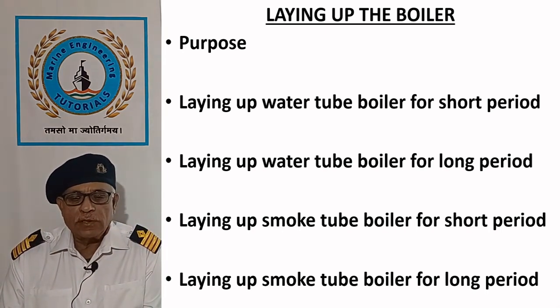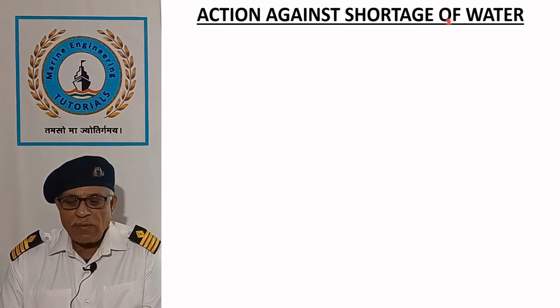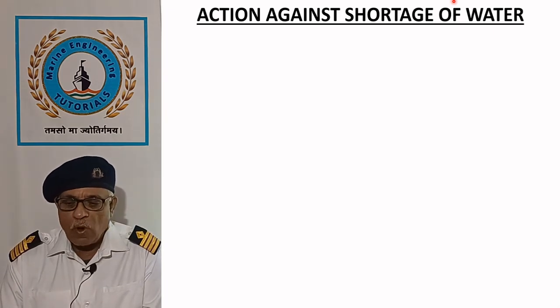Action against shortage of water. Rapid drop in water level or heavy loss of feed water indicates failure of heat transfer surface, which may be confirmed by release of steam from exhaust stack.